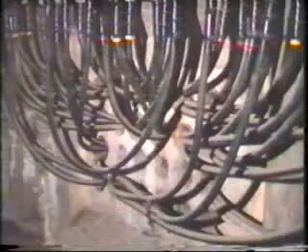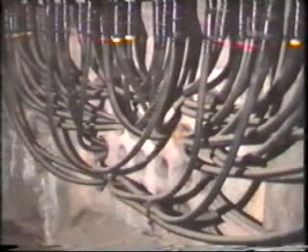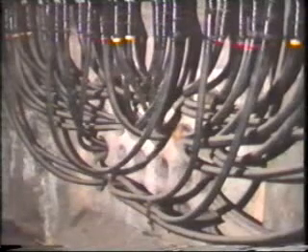This condition is more likely to occur where voltages are 12 kV and higher, and also where the line capacitance is high, for example with long lines or where cables are used. When you think of all of the variables in the circuits, this subject of ferroresonance is obviously highly complex. But it is essential that we understand the principle, because we shall be meeting this term in future tapes when we discuss specific installations.